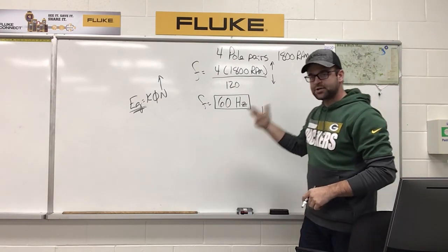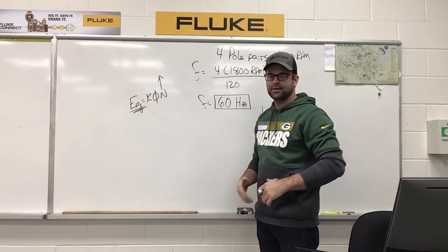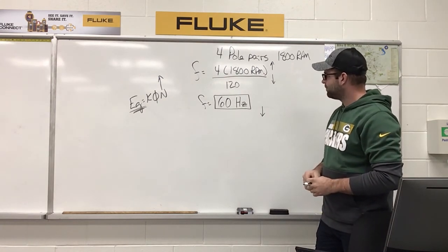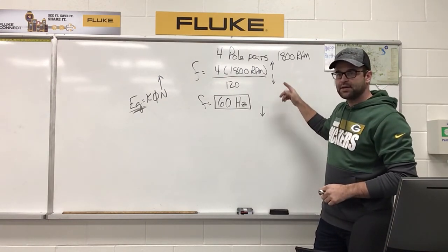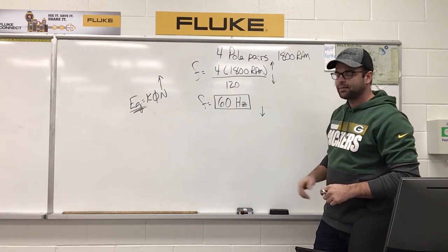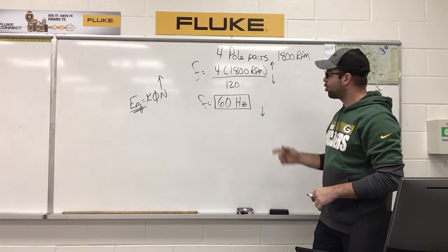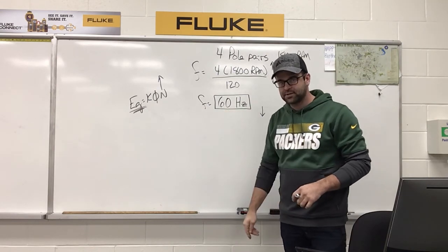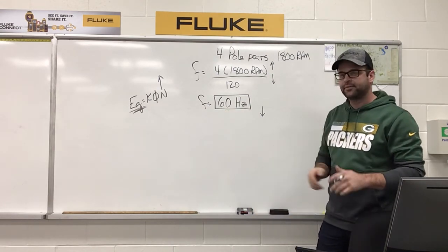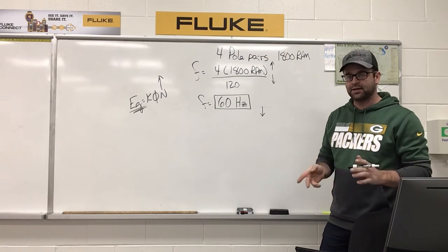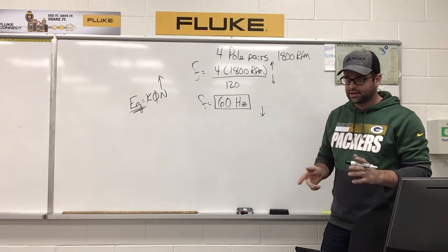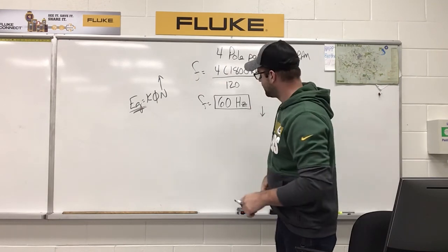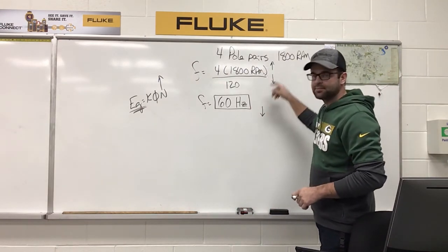Especially if you go to install a generator, let's say it's on a house, it could be a single phase generator. You need to make sure that the speed of the prime mover on that generator is going at rated speed, otherwise you won't get the rated frequency of it. And if that frequency is off a few percent either way, it can be harmful to the equipment that you're running. So very important that speed is maintained the same.